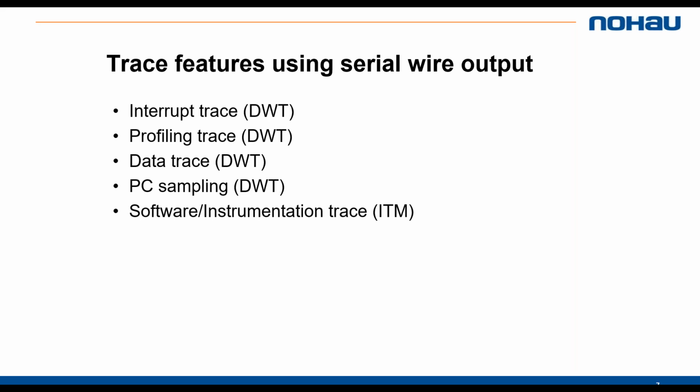I will come to that in my demo later on. And then you have data trace, and with data trace you can specify a certain variable or memory address that you are interested in, and you can see the accesses, the reads and writes, and the value that is read or written from this address.